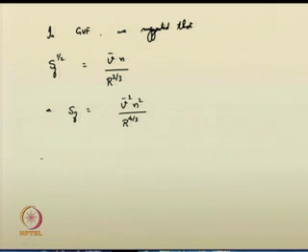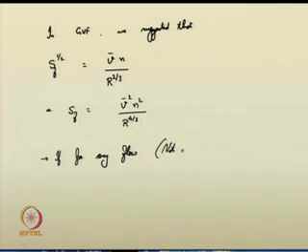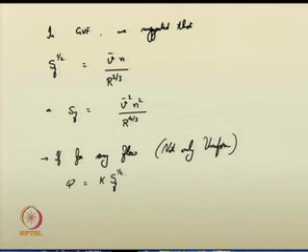If, for any flow that is not only uniform, we apply the Manning's equation, you see that your discharge Q can be computed using a conveyance factor K into the square root of the friction slope.